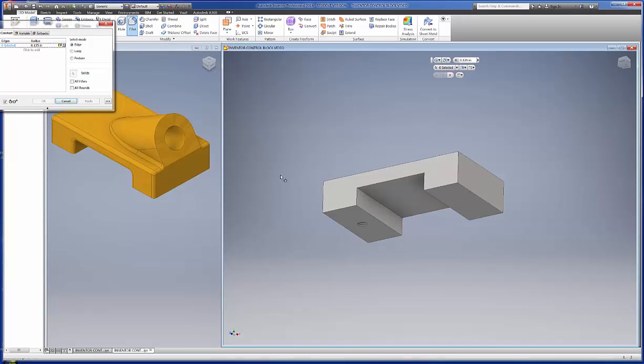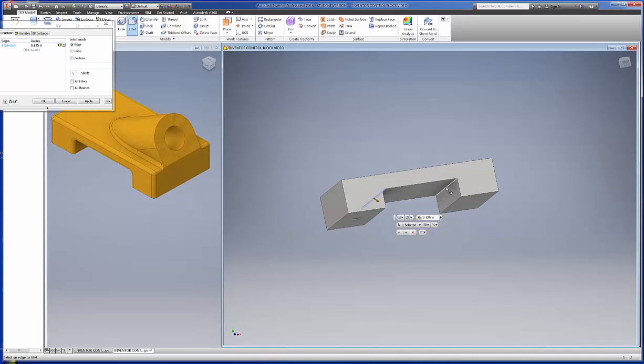The fillets on that need to be 1/8 of an inch, I believe it says, unless otherwise specified. So we'll go in here and we'll pick this edge here, rotate that around, pick that edge there, and we can accept that. Just hit apply if you want. Now we could go ahead and fillet this edge here, all these vertical edges basically.